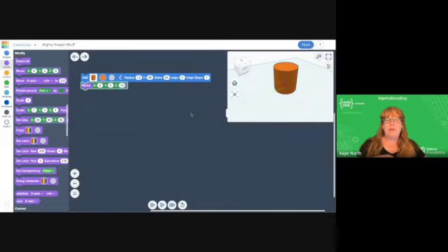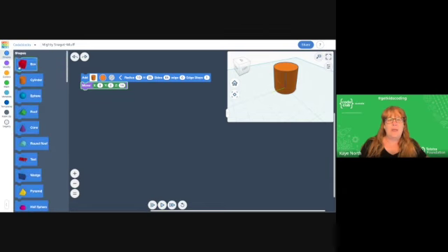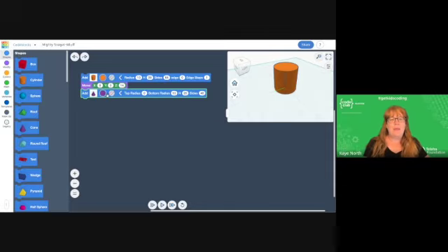Now we're going to create that hole in the middle. We're going to do that by creating a shape with two cones inverted and a cylinder to join them on the inside. We're going to go back to our shapes and grab our first cone shape and expand it out. Now in this one, we need to select creating a hole.